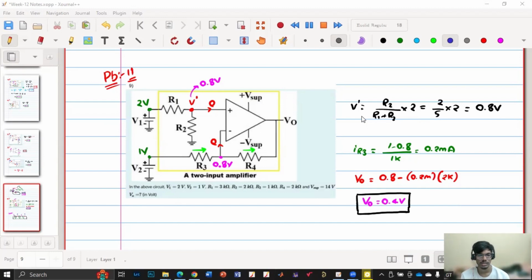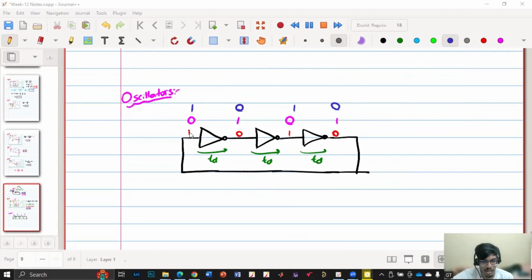No, actually, there are two different things. A comparator, for a given input, will give either plus or minus. If you fix the input, the output is fixed. But in the case of an oscillator, it is an iterative process. Even in this digital oscillator, if I initially give a one here and leave it, this one will propagate through 0 1 0, and it will keep on changing.